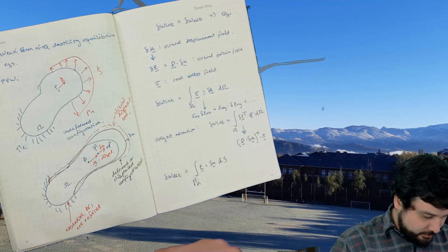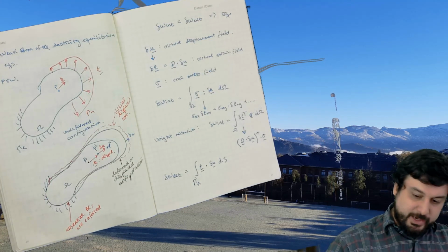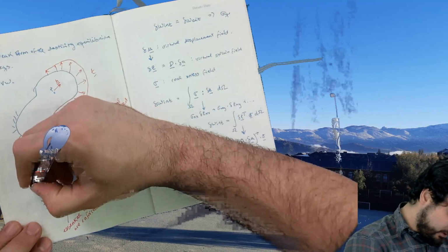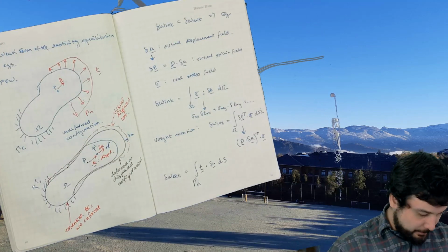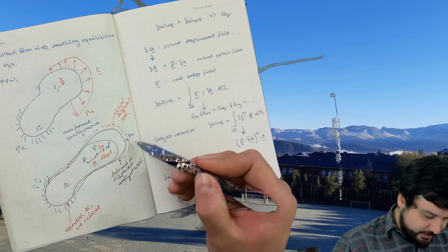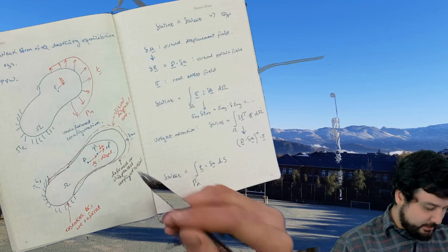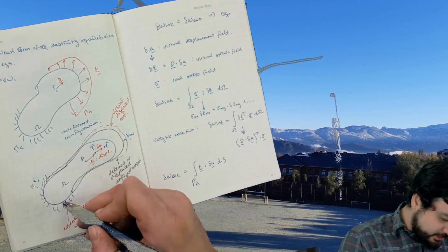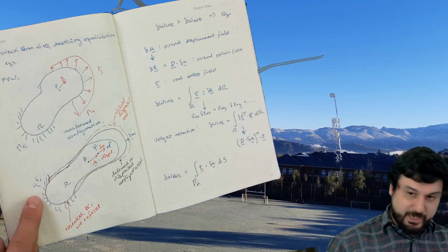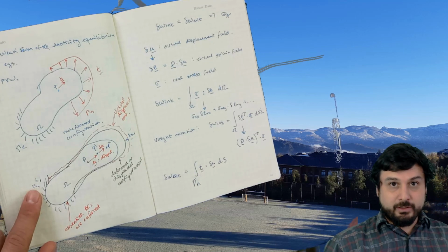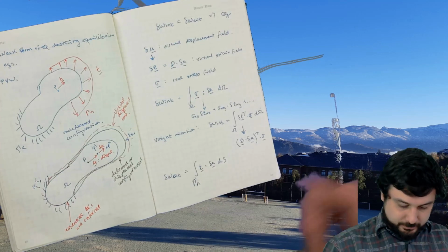And at the essential boundary conditions, we know that there are reaction forces. We know that there's some sort of forces that enforce that boundary condition. But since we require that the delta U, that is the virtual displacement of the body, meets the essential boundary conditions, that means that there's not going to be any displacement there. And that means that these reaction forces, while they're there, they don't do work, so they don't appear in this equation. Okay?